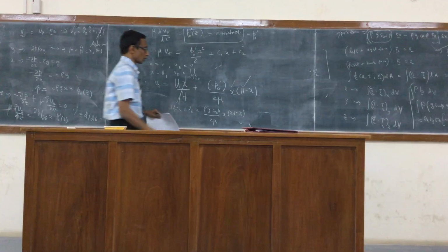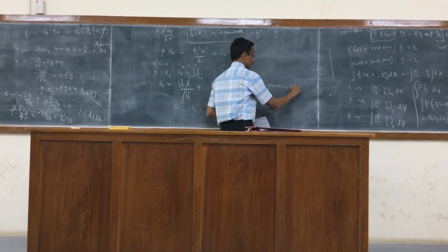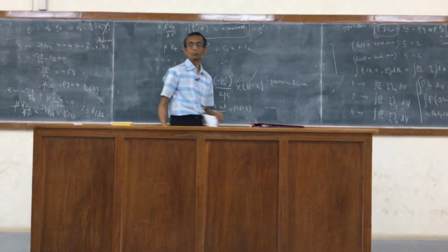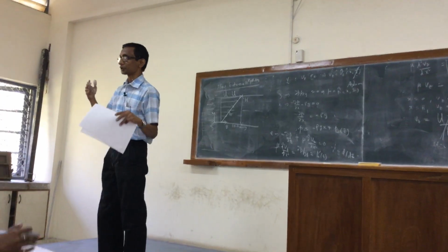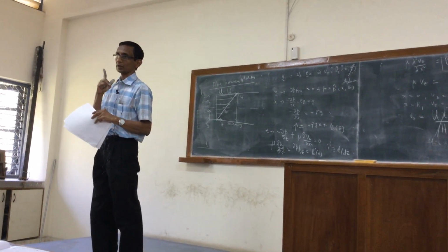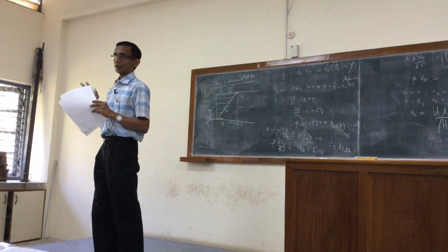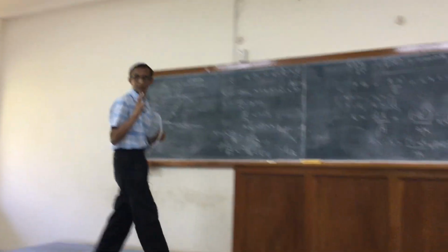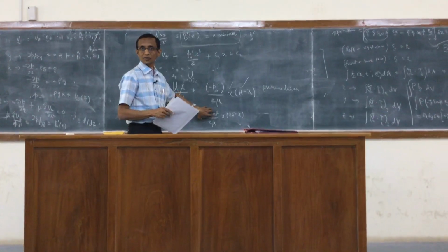This may be what is called as a pressure-driven flow. So there is no gravity that's driving the flow. The earlier case, if you saw, there was no pressure gradient in the flow direction at all. In spite of that, P varied only in the X direction, and effectively turned out to be the hydrostatic pressure. Right? There was no variation in the Z direction. Right? So the flow was still possible because of the effect of the gravity.